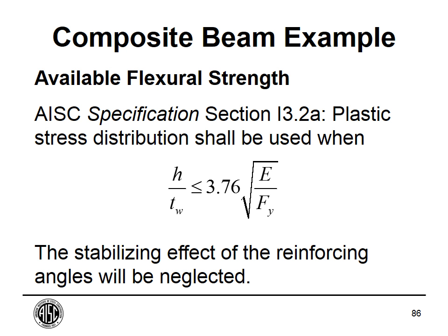But before we do that, what we want to do is use the plastic strength of the cross section. But to be able to use the plastic strength, we need to make sure that our web can handle it without buckling. And the way we would check that is to make sure that the slenderness, the lambda of this web, is less than lambda sub p.